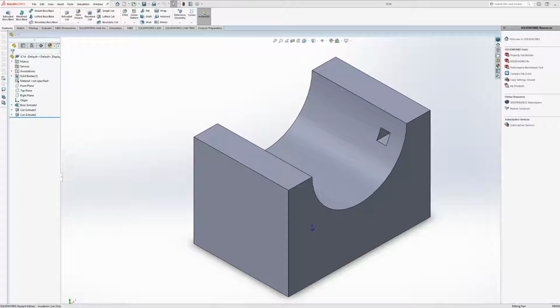But once you make that flip, all further dimensions shown will indicate that specific unit. So if you flip over to IPS, all of the dimensions from there on out will be in terms of inches or pounds or seconds. Changing dimensions is going to be the button at the bottom right. It should say MMGS or IPS. When you make that change, it will flip all the given dimensions.